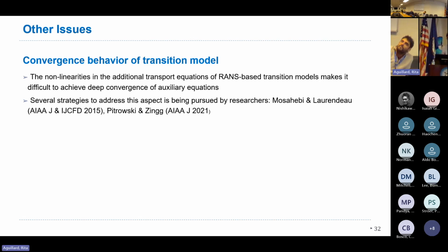Although depending on the scenario, say for a separation bubble, the streamwise resolution is a lot more important than wall-normal resolution, whereas for TS-based transition, streamwise resolution is equally important. So that kind of changes. That is the current identification we have within the group. Yeah, thank you.